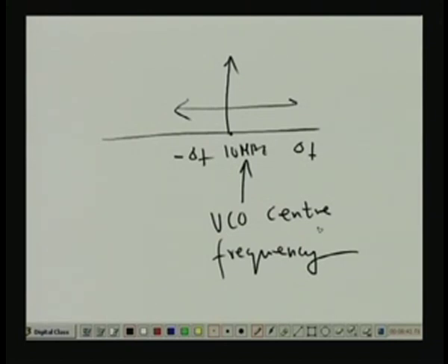So, this 10 megahertz signal, over this I am getting a shift, right. On both sides you will get a signal, and how much the shift will be depends on the DC voltage, because the input to the VCO is the DC voltage. How much the shift is will also depend on the mark-to-space ratio of the PWM, and the mark-to-space ratio of the PWM will depend on the unbalanced voltage of your Wheatstone bridge. So, the frequency shift around 10 megahertz of the VCO will depend ultimately on the signal which is coming from the unbalanced voltage, right.